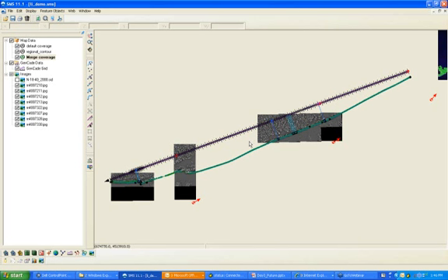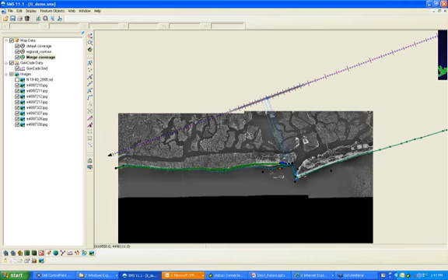You'll see we have our wave information. We also have all of our other information for the breakwaters and the bypassing also entered. If I zoom in this area where I have the additional information, you can see right away that we have a constant cell size between the 2 refined points. And then it gradually increases until we get to the largest size.